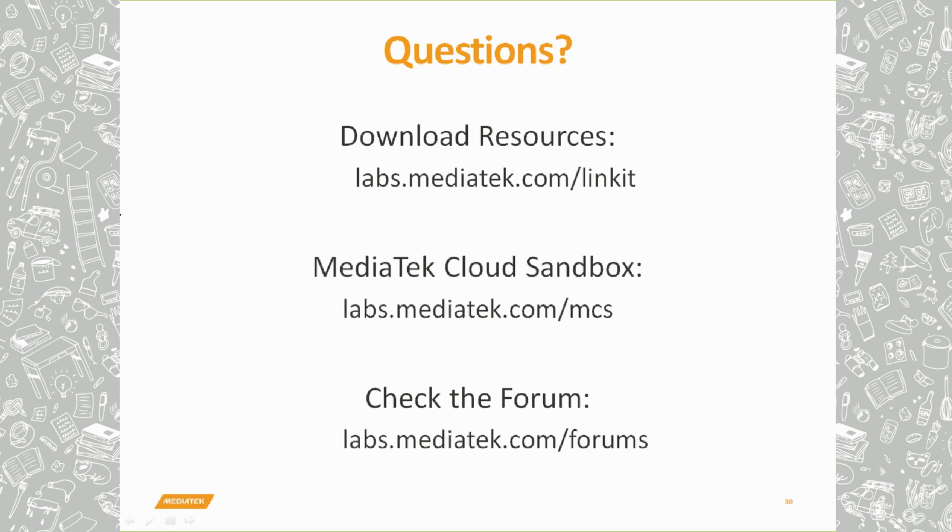As I just mentioned, the LinkIt Assist 2502 is based on the MT2502 as well, and the SDK is a C SDK which plugs into Eclipse, which gives you much more access to the hardware itself and to the performance of the chip. This SDK also works with the LinkIt ONE board, but before you can use it, you would need to update to the latest firmware.